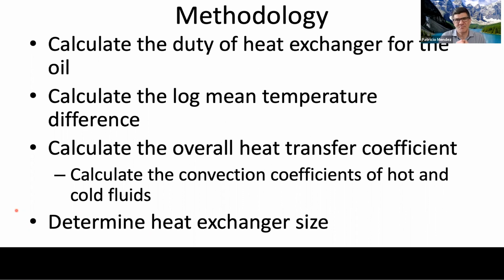And many others of us will do heat exchangers from a specification. But it is my dream that we'll keep inventing new things and being always at the forefront of technology. And with what you're learning here, you can. Okay, so we calculate the heat transfer coefficient. For that, we need to calculate the convection coefficients of hot and cold fluid, sometimes the conduction through the pipe, and an assessment of fouling. And then we determine the heat exchanger size.